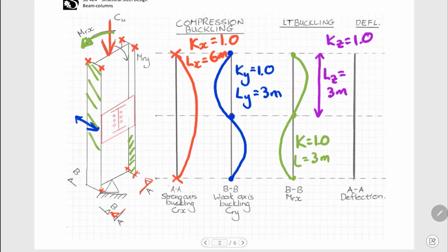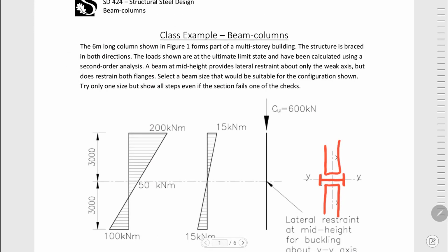But let's have a look then at the deflected shape, as the structure is loaded. Let's have a look at the bending moment diagram here. You can see there's maximum bending. Remember, the curvature is proportional to the moment. So we've got maximum curvature. The curvature gradually decreases until there is 0 curvature, and then it curves the other way. So we have double curvature in this section.